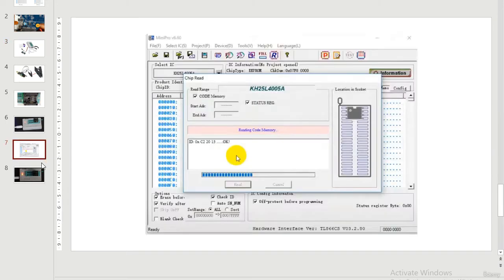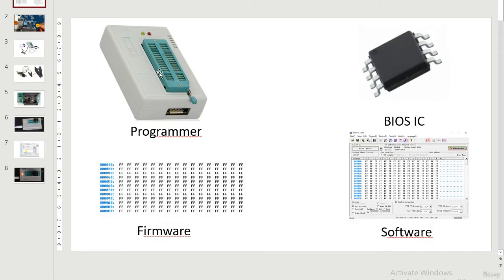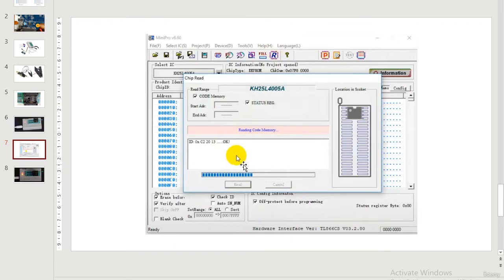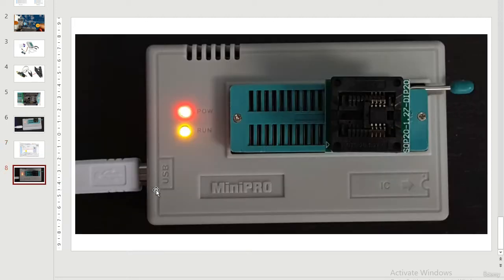Okay, so of course, after connecting the programmer to the laptop, you put the BIOS chip in the EEPROM and install it. Then you can launch your program. You can go to the software and choose program, and then the programming will proceed. When you program the BIOS, as you can see here on the EEPROM programmer, there are two LEDs.